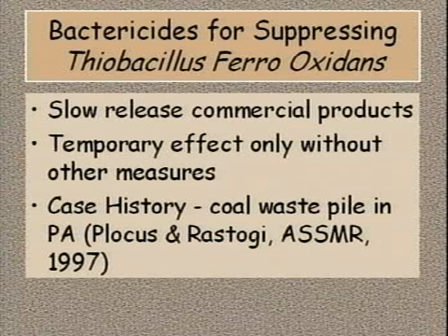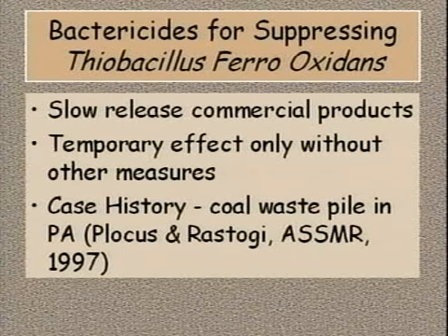That had some ARD hotspots. These had been identified using geophysical techniques. This site in Pennsylvania had an acidic seep with pH 5 to 6 at the base of the dump. With lime addition to the discharge, a small wetland was able to treat the flow.